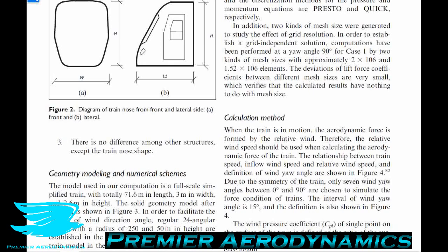Also, when you try to use this data for your CFD validation, you're going to have problems validating your CFD. You're going to have some things that will line up, other things that won't. In reality, nothing actually should be lining up properly because you have errors. And if they do line up, that's just fluke. And you can't really trust your CFD anyway. So you need to know what the density of air error is in your experimental data so that you can then map that to your CFD and at least factor that in when you validate your CFD against your experimental data. That saves yourself a lot of headaches.